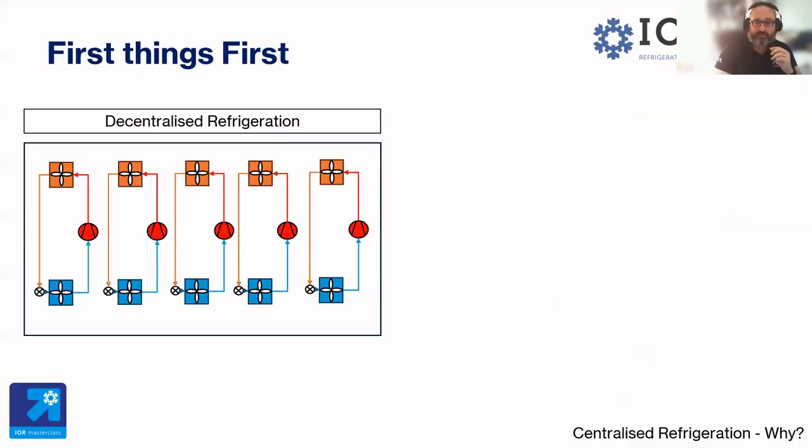So first things first, we're going to define our conditions. We're going to take a hypothetical ideal refrigerant, and refrigerant choice will have an impact on what systems are possible to adopt. But again, we're just going to go with the concept. So we're going to assume we've got 5 condensing units each with 1 evaporator rated for peak day duty, 1 compressor rated for peak day duty, 1 condenser rated for peak day THR, and 1 expansion device.